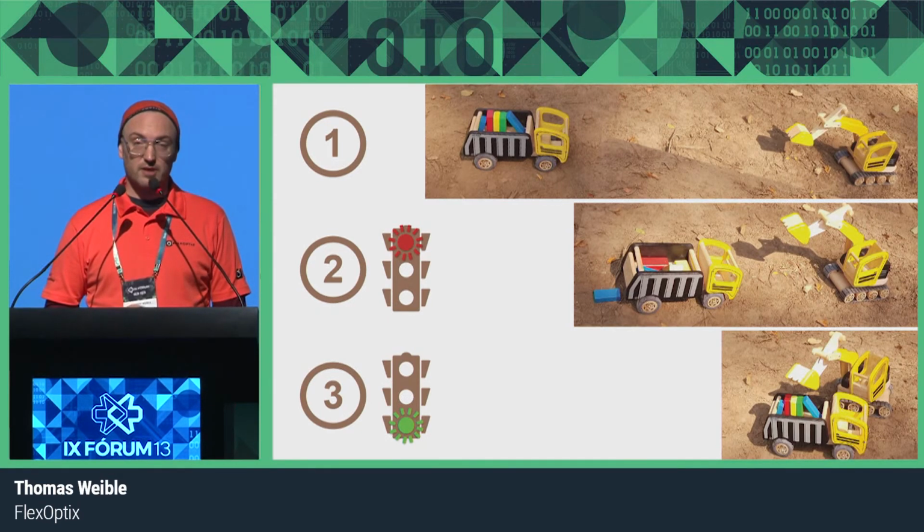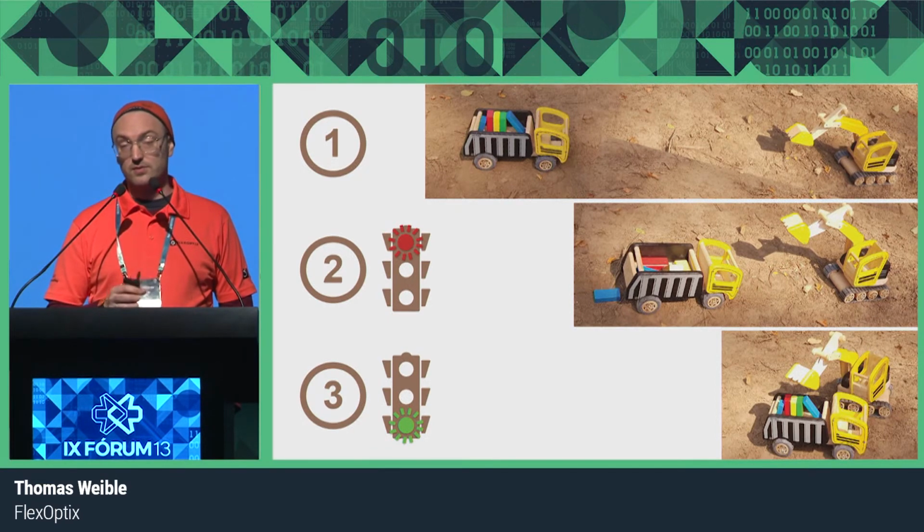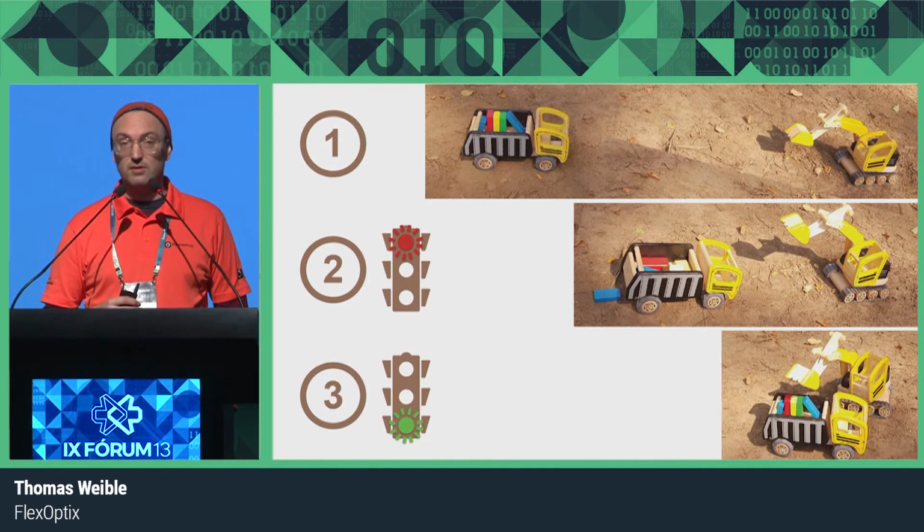Now, how powerful is such a FEC? This is also quite interesting to see. When we take those 1,500 bytes, when we do our math, this is 12,000 bits. When the errors are equally distributed all over that frame, we can correct roughly 330 bits. And when the errors are clustered at a certain spot, then the performance goes down to roughly 33 bits which we can correct. So now you get a rough idea how powerful it is.